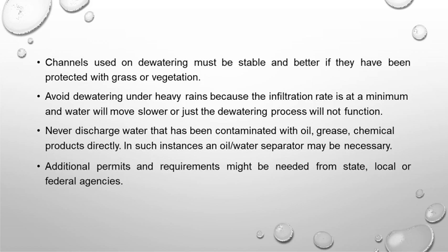Okay. So as we know, a pump is a mechanical device which is used to increase the pressure energy of a fluid, and pumps are used as a water handling device in construction projects. These pumps are broadly classified into two types. The first one is the positive displacement pump and the second one is the rotodynamic pump. The reciprocating pump and rotary pump are examples of positive displacement pumps, and the centrifugal pump is an example of the rotodynamic pump.